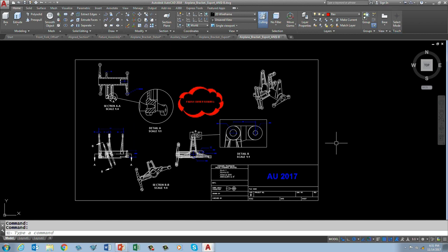So if you look at the very last page, page 27. All right, 26, 27. You can export a sectional view. But when you export a sectional view in AutoCAD, you get extraneous lines because AutoCAD sees it perfectly and then puts that extra line that's there.